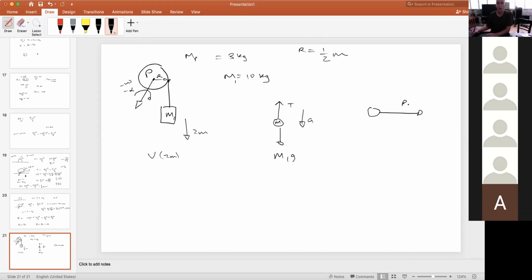At a distance r, we have a tension T. And if we put those two vectors tail to tail, we see that when we turn r to T, the angle between them is -90, which means this is a negative torque. Also, alpha is negative. So when you do a torque diagram, I want you to write the r vector, the force, in this case T, and which way the whole thing's rotating, because we could have another mass over here, so we could have another r and another T if we needed them, but which way it's rotating and whether or not the torque is negative or positive.